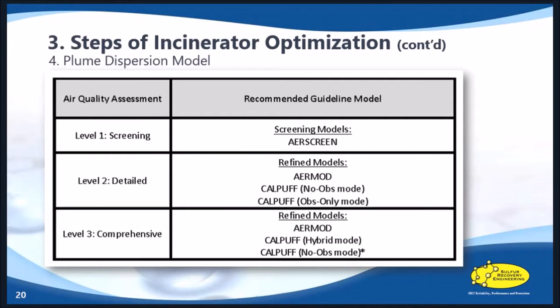This dispersion model uses mathematical formulas to characterize the atmospheric process that disperses a pollutant, like SO2 in our case, into the surrounding atmosphere or vicinity. Based on emission and meteorological inputs, a dispersion model can be used to predict concentration at selected downwind receptor locations.